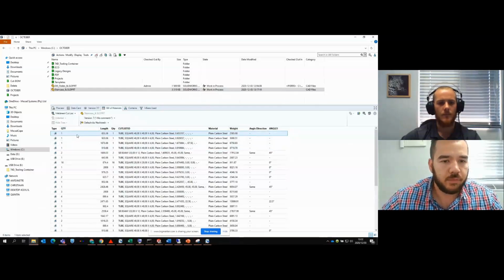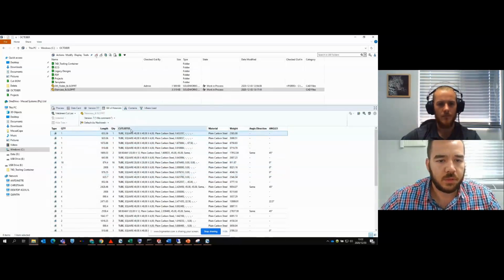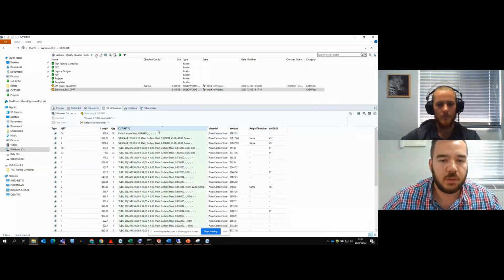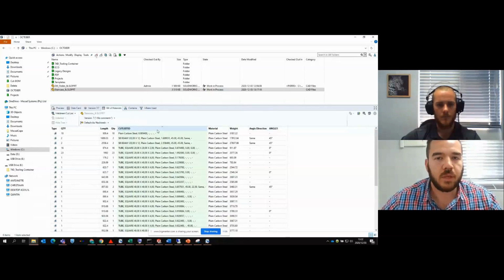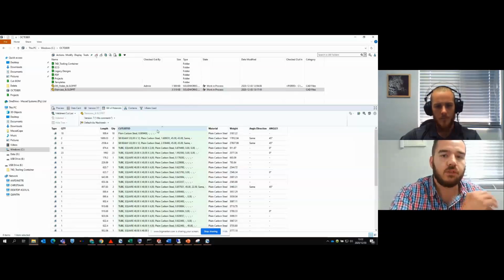I can have, for example, my quantities and the different lengths. Here you'll see I've got a duplicate of the quantities, but then the Cutlist ID. If we concatenate all of that information, it's very easy to come into PDM and sort them. So when we send this out to our Excel spreadsheet, we can easily filter. For the companies that bend or cut their own piping, they can filter and put it in job files. So it's just a lot easier to do now in PDM 2021.